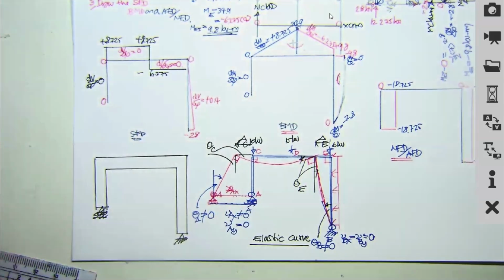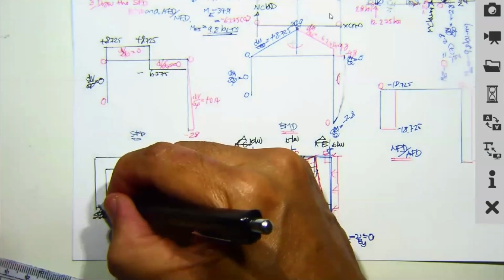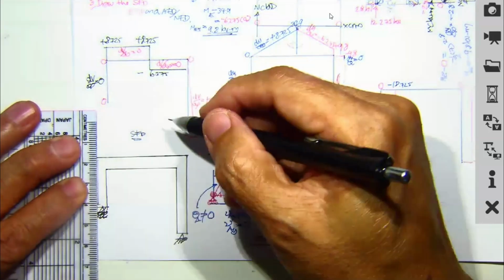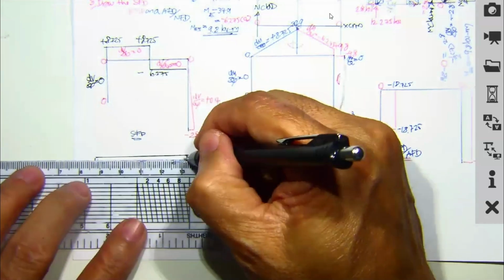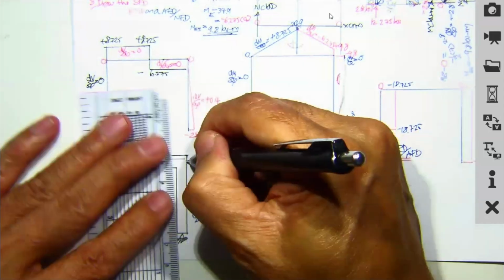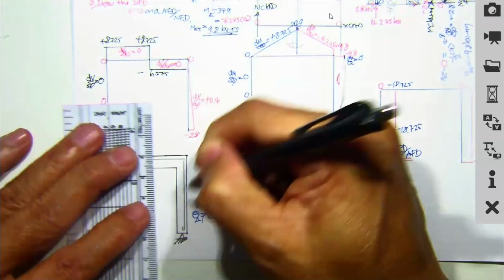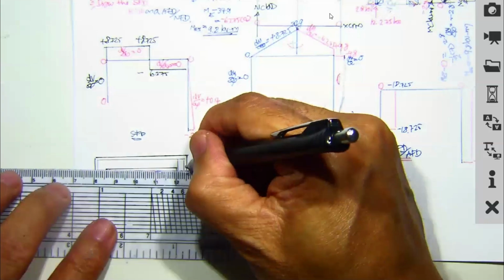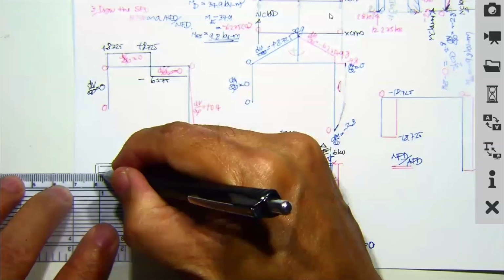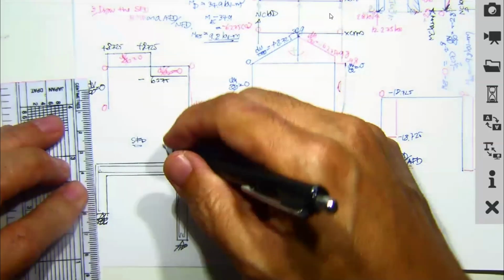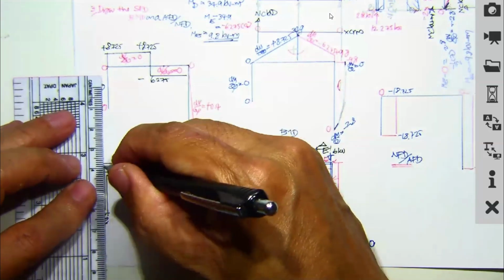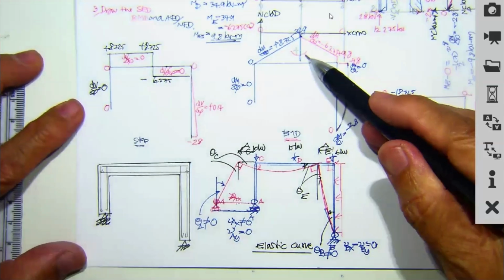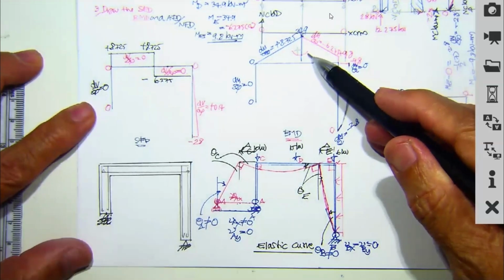For the reinforcement, most of the time we will have the minimum requirement of reinforcement, and we just follow that. Such as for the column, we must have 1% reinforcement. Then following what we have here, we only use this one to put extra reinforcement.